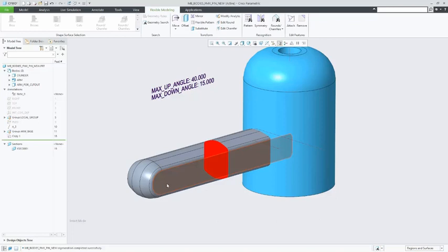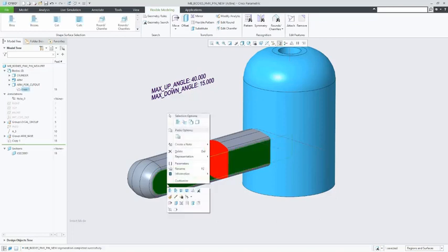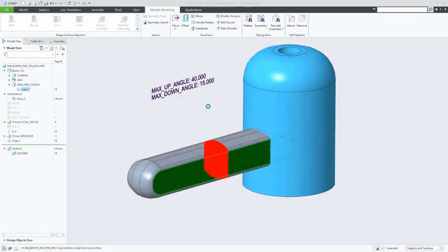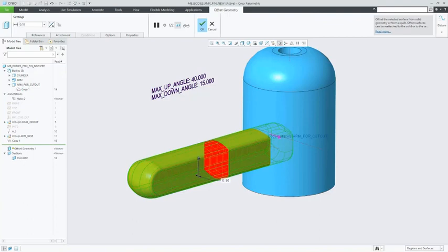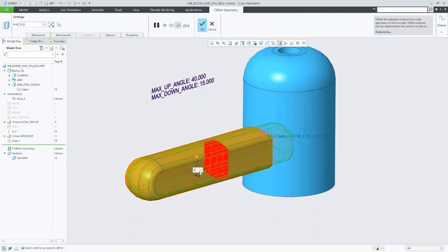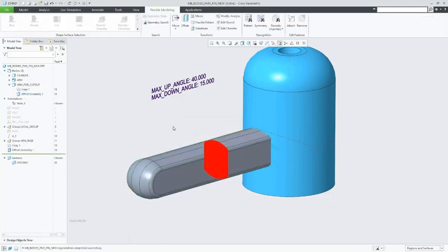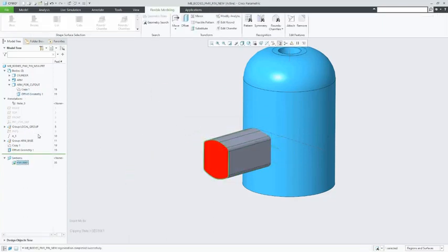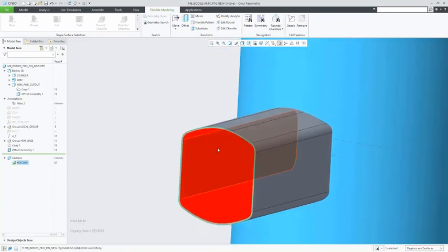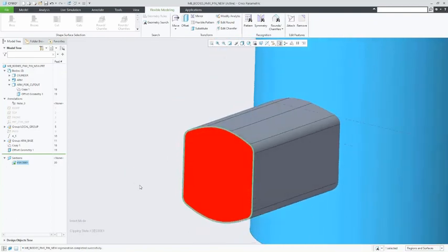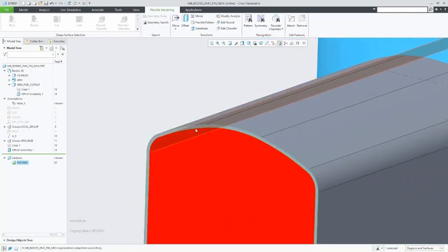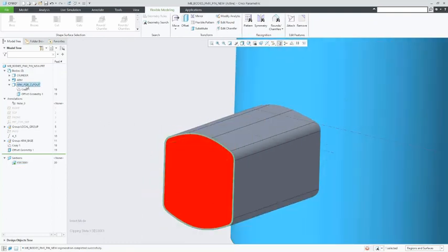Now what we're going to do is apply a clearance offset onto the shape of the cutout body. To do that, I use the select all body surfaces option and use flex modeling offset of 0.5, for example, to create the offset. That should give us a difference now, as the interference is only matching to the size of the original arm body, and we now have a gray shell frame border around it due to our offset we just applied.